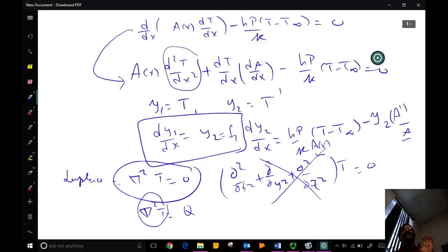Now, COMSOL has made it easy for you. For example, if you're doing fluid mechanics, there's a fluid flow module. If you say Navier-Stokes equation, that's your template. It pulls out the continuity and momentum equation. You define your geometry, you do the meshing, and set up the boundary conditions, initial conditions. It solves it for you. So the same thing has to be done for this particular problem.